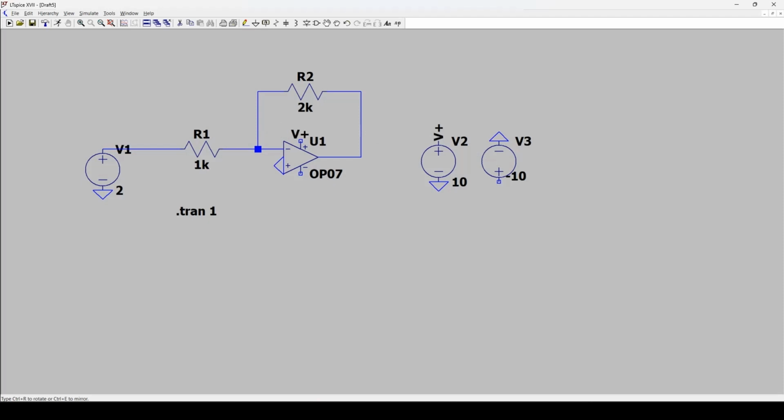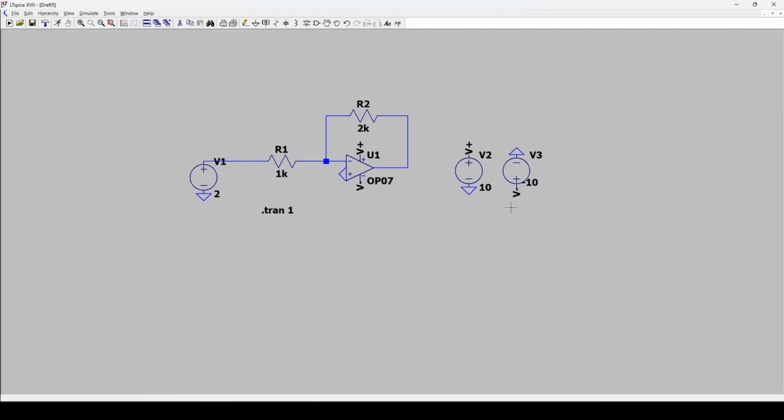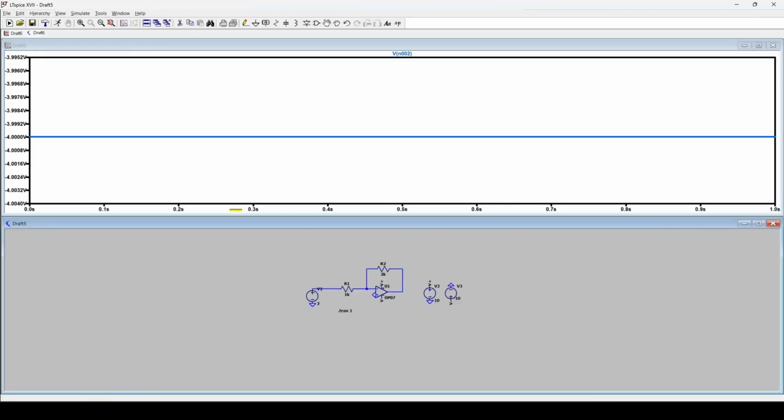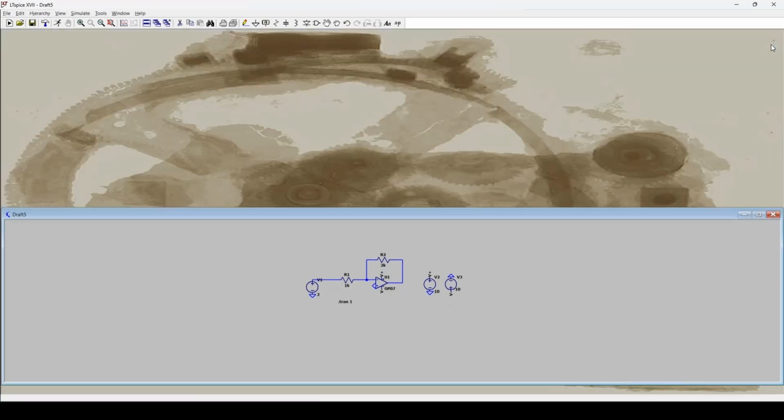And then I'm going to connect it to the positive input of my op amp as well, positive power supply input, excuse me. And then I'm going to connect it here again for my negative supply as well. But I am going to change this negative name to V- to denote negative power, and the same thing for this. And so now anything that is connected to V+ will be connected to the 10 volt power source. Anything connected with V- will be connected to the -10 power source. And just to verify everything's working fine, we can run the simulation again and see that we're still getting the same outputs as before. So we know we didn't destroy anything, we simply connected things a different way.